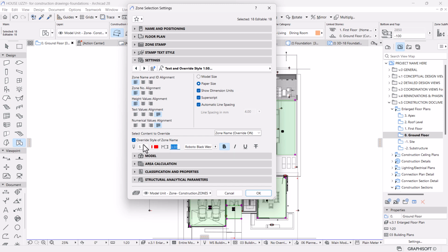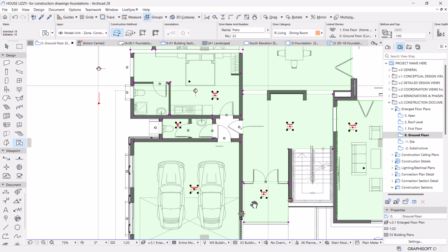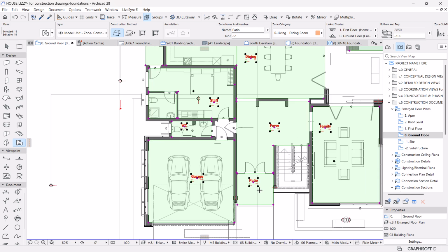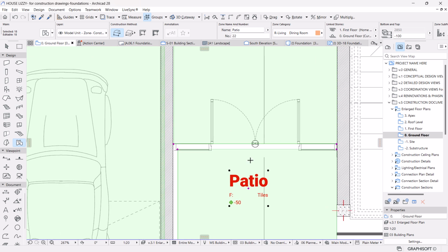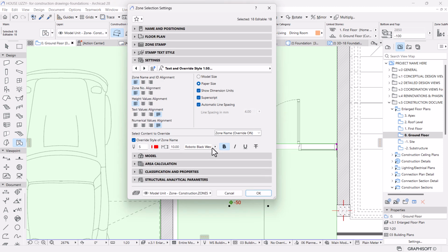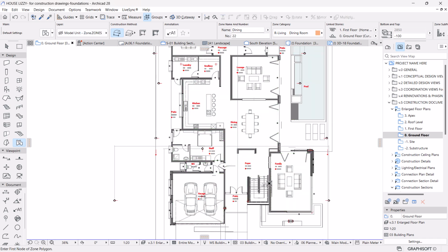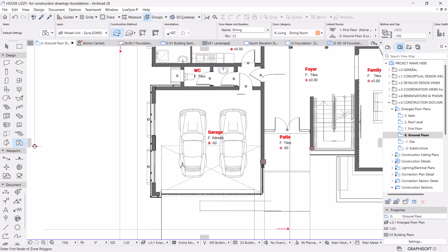What we need to do is to open the settings and try to override the height. Let me start with this one, make it 5. Yes, 5 still is too small. Let's make it 10. Yes, 10. The problem with this, we are only changing the title or the room name instead of all the elements. So I'm gonna go back and change this to text block, override, make it 8. Yes, that's what I want. Perfect. Okay, so we have that.